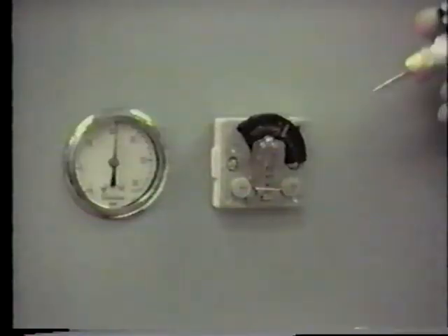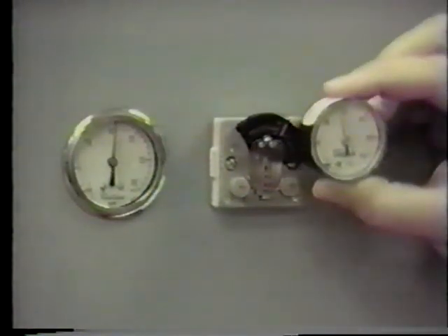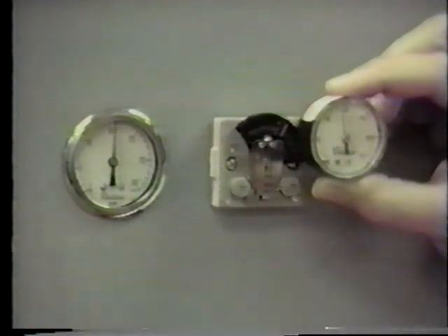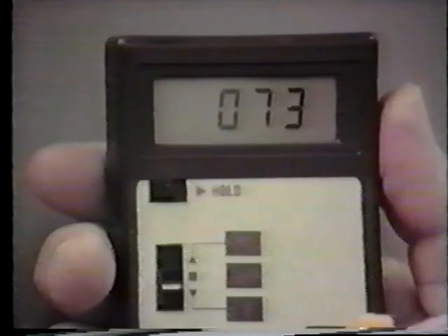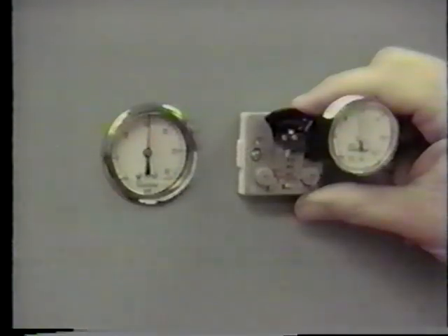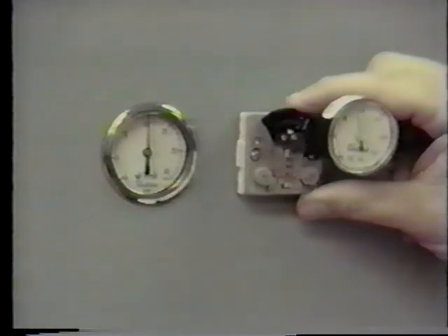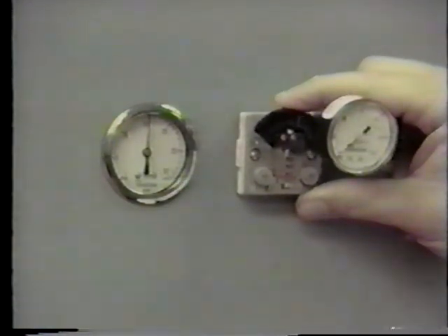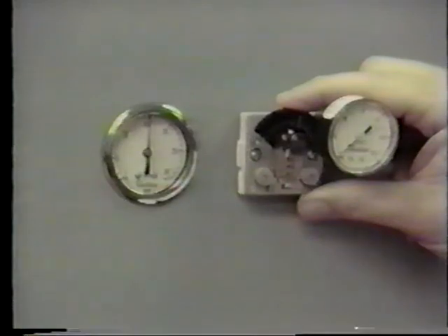To calibrate the summer-winter thermostat, install a gauge and branch line tap adapter in the branch tap hole. Measure the ambient temperature with an accurate thermometer. Move the set point adjustment to the measured ambient temperature using the scale cast in the body of the thermostat. Take care not to breathe on or touch the bimetal, or an inaccurate reading will result.